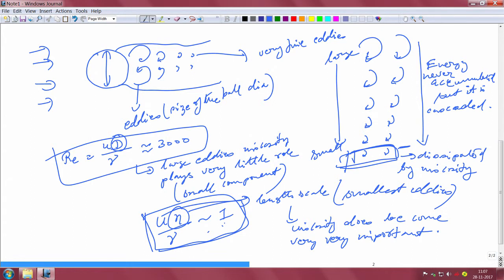Okay. The energy is never accumulated, but it is cascaded down, and turbulence is a highly initial and boundary condition dependent phenomenon. It amplifies any small differences. However, if it is a statistically stationary kind of system, the statistics will actually match.